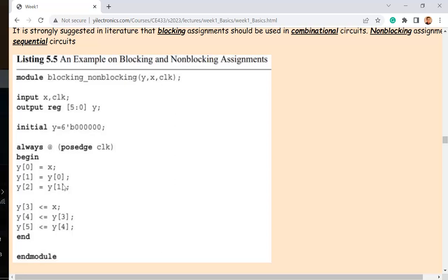So you have the same digital circuits. You cannot get an engineer here and say, I need another state, just update it for me right now, right? Tape out another circuit for me or reprogram it. It's not really realistic. It's just the digital circuits with different states, and how to update all the states. You have to have some trigger or stimuli to make it happen, and that stimuli is literally the clock. So the clock is going to update the digital circuits to make it into different states.